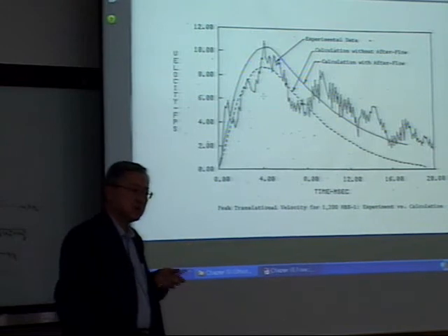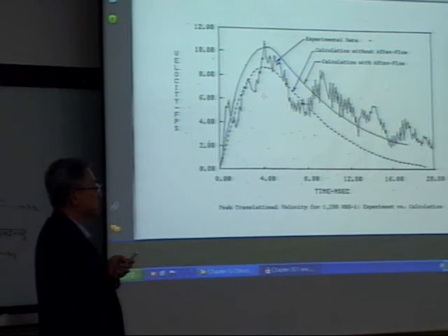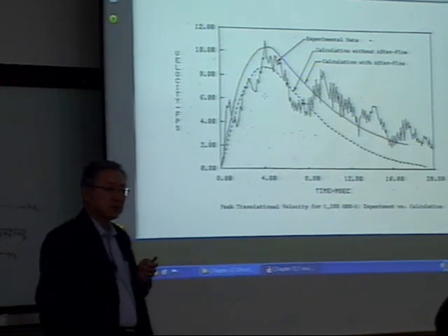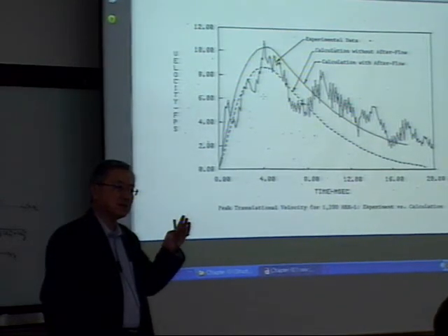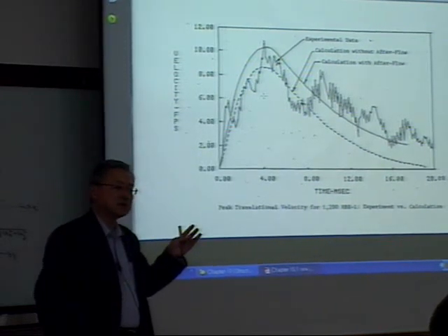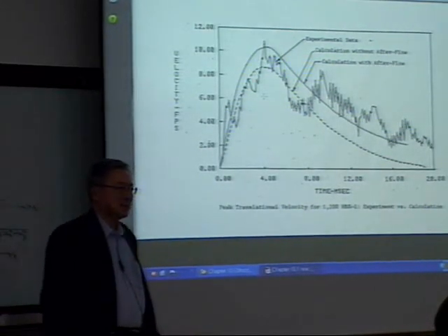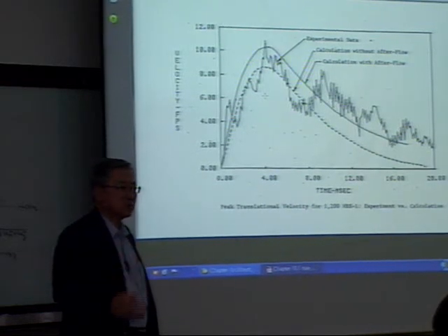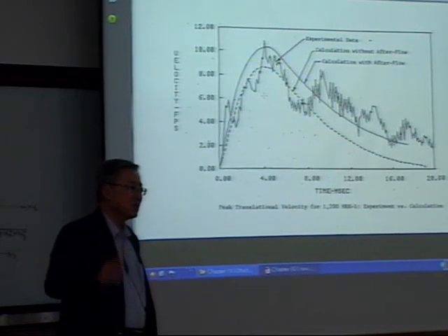Using the spherical wavefront provides a lot better agreement compared with the experimental data. Okay, in this case the R, the standoff distance, has to be not 1,000 feet away. Forget it. This converges to this because the second term effect is almost none, because it's proportional to 1 over R.